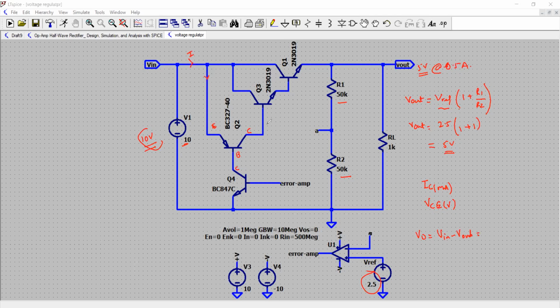Then you have a collector current, right? And it will flow, it will become the base current of this NPN transistor, which is a part of the Darlington pair. This is your emitter again, and this is your collector. So here your IC, and here your IE. Then this current goes ahead right here, which is the collector current of this NPN transistor.